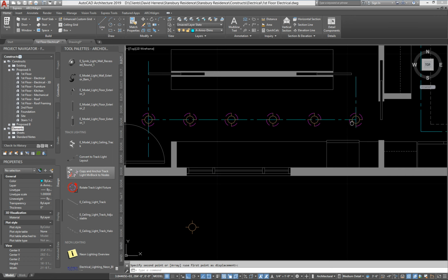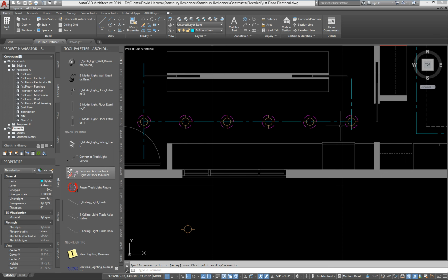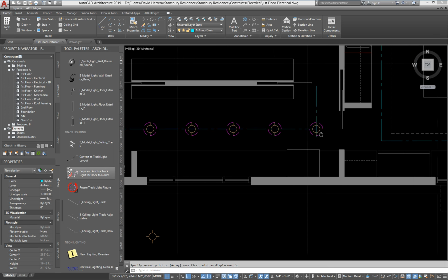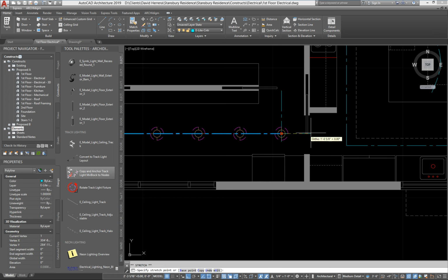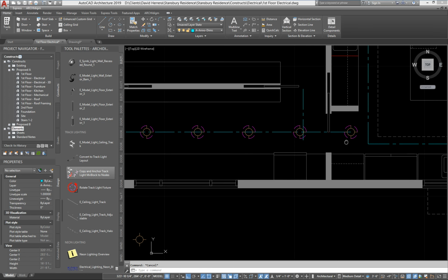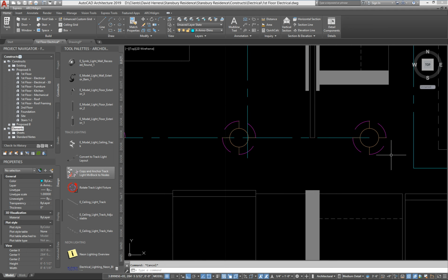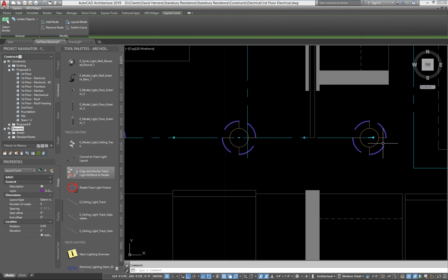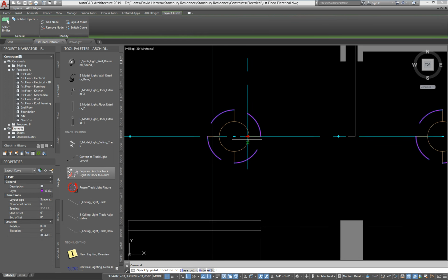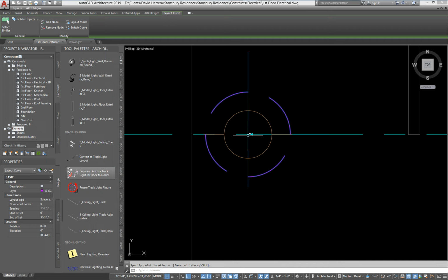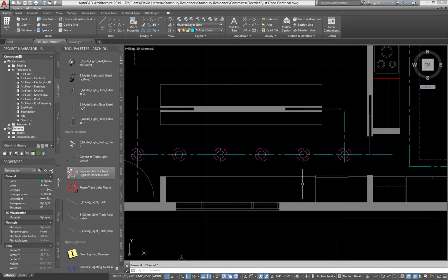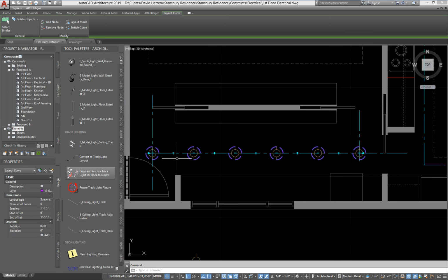Now in this particular scenario, I would like for the contractor to see that this center line is centered in this door. So graphically, I want this to come out like that, and I'll probably put in a little CL symbol. But that messed up my whole lineup of lights. I don't want the lights to do this. So what I'm going to do here is grab that last node and drag that back and do the offset to here like that. So the line work does what it needs to do, and the layout curve does what it needs to do.